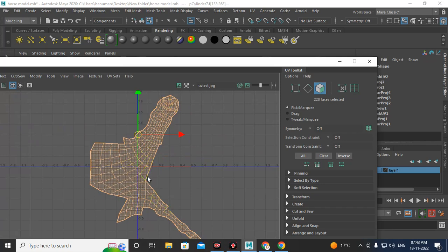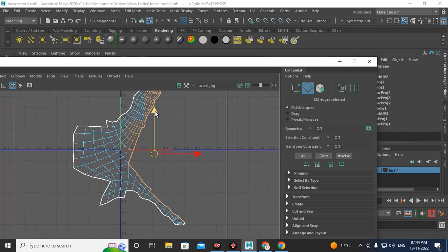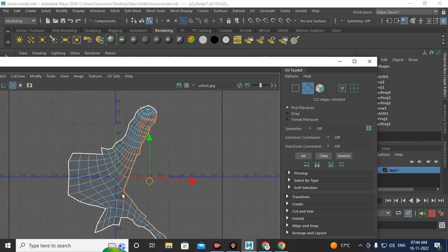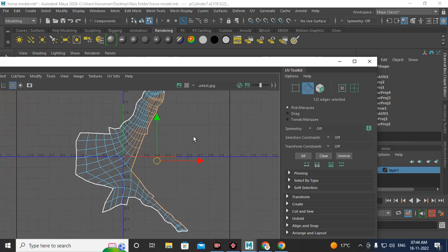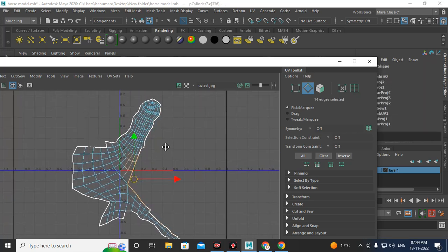And where we got cuts roughly and randomly because of the projection, where it is open, that also you can join again like this. Select these edges. See, this side I am selecting all the edges. Okay, so whenever I select one side's edges, the opposite edges are automatically selected. Okay, see this. Yes. Here I am selecting the edge.